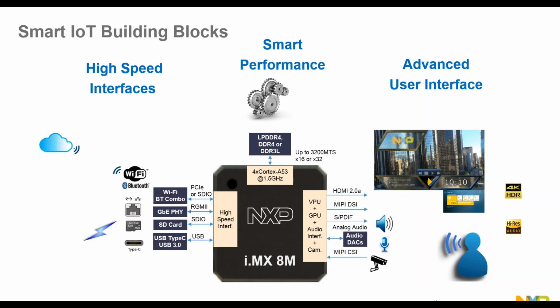On the topic in question here of interfaces, you have multiple interfaces used. So HDMI 2.0 used to connect to low cost and even high performance 4K monitors for broader, bigger screens. You have a local MIPI DSI that you can drive, for instance, a 7-inch or 5-inch OLED display at 1080p. Several audio interfaces, digital microphones, and outputs for codecs.